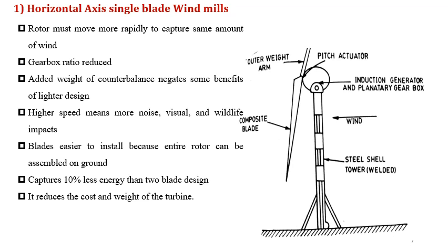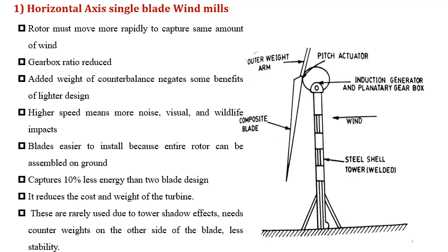Adding to this, we can see some more advantages. Advantages like simple blade controls, because of lower blade weight and cost, and lower gearbox cost. So the counterweight costs less than the second blade or two blades. The counterweight can be inclined to reduce blade coning, and pitch bearings do not carry centrifugal force. The blade root spar can be of larger diameter, okay.